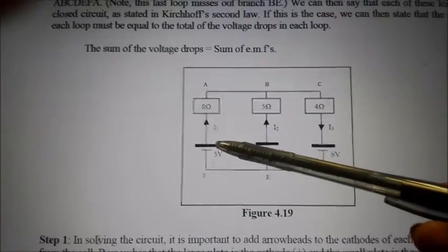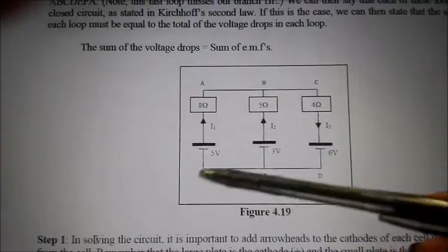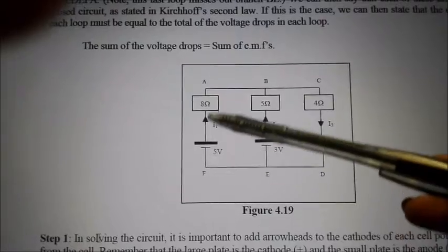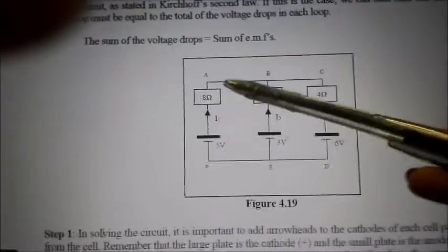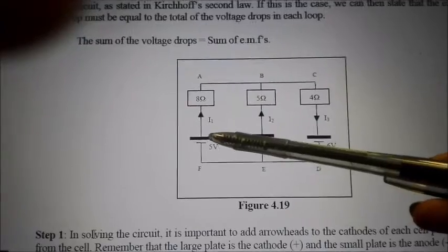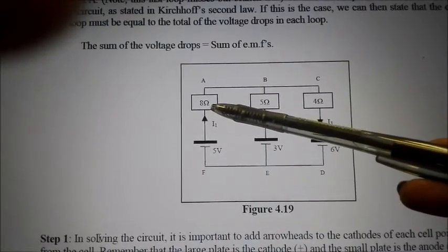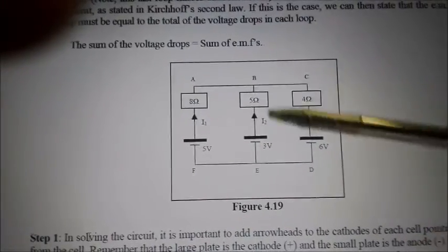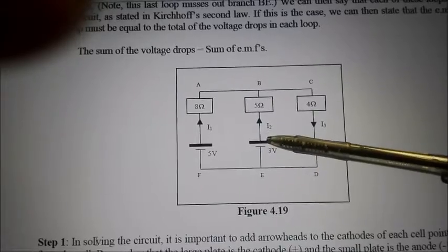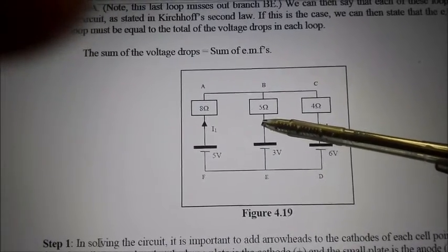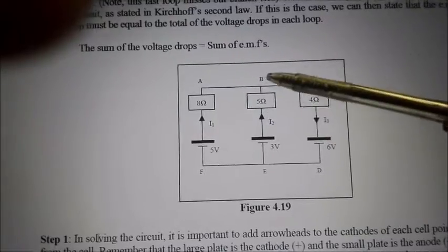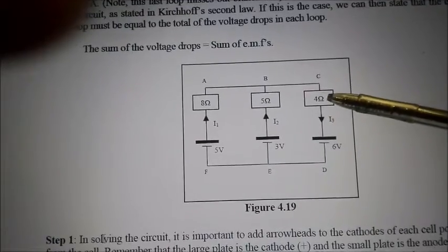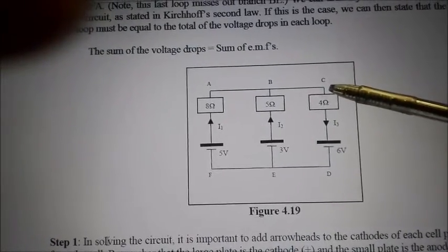If we're looking at this power source, we see that this shorter line is negative, the longer line is positive. We see the current is exiting the positive and entering this resistor. Therefore, because it's coming from the positive, going to the resistor, we would denote this area as positive and the top area as negative. The same would apply here. We see a negative, positive. The current is exiting from the positive direction, therefore we would have a positive and a negative. Current 3, however, is exiting, which therefore means here we would have a negative and there at the top we'd have a positive.